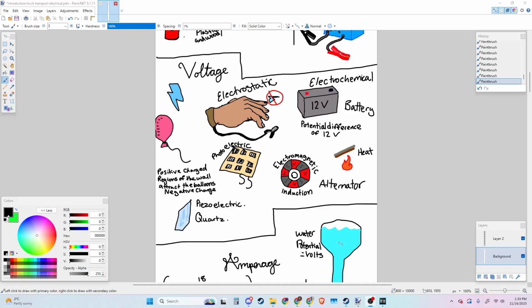And we also have this piezoelectric quartz here. Piezoelectric is very interesting. Most common piezo is quartz, and you need a specific crystalline structure for it to work. It's not going to work with your standard kitchen countertop. When quartz is compressed, it causes the tiny quartz crystals to be unbalanced, adding a voltage potential on each side. It's a very small voltage, but also keep in mind that if you do the exact opposite, instead of compressing it, you apply voltage to the crystal, it'll expand.